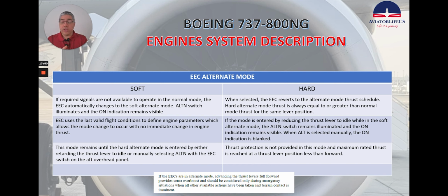Now, this small note here says if the EECs are in alternate mode, advancing the thrust levers full forward provides some overboost and should be considered only during emergency situations when all other available actions have been taken and terrain contact is imminent.